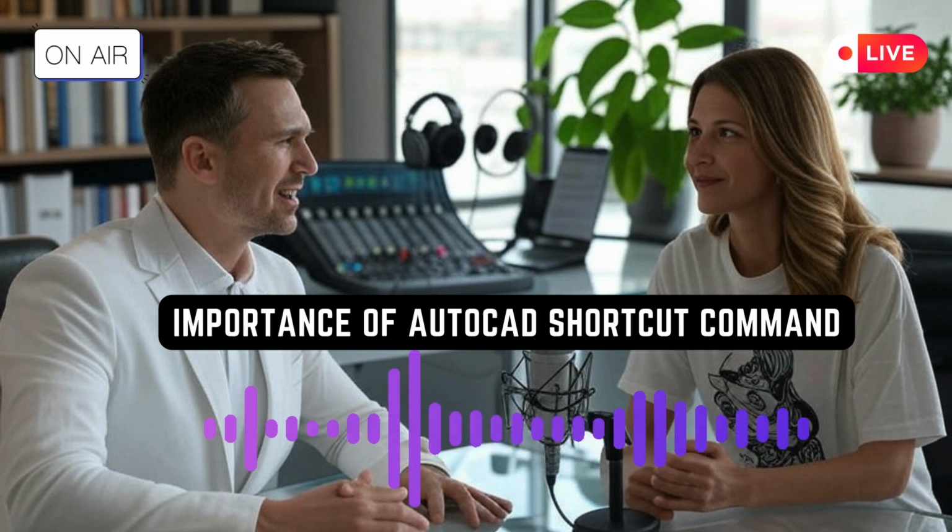And I'm guessing there are some for viewing and drawing as well. I mean, zooming in and out, that's got to be a pain to go back to the menu. Oh, yeah. Z for zoom is essential. Just Z by itself activates the zoom tool. But you can also do ZA to see the entire drawing or ZP to zoom to a specific area. Oh, so you've got options. Oh, yeah. You're not just stuck with the basic zoom. That's really cool. Okay, those are some pretty practical ones.